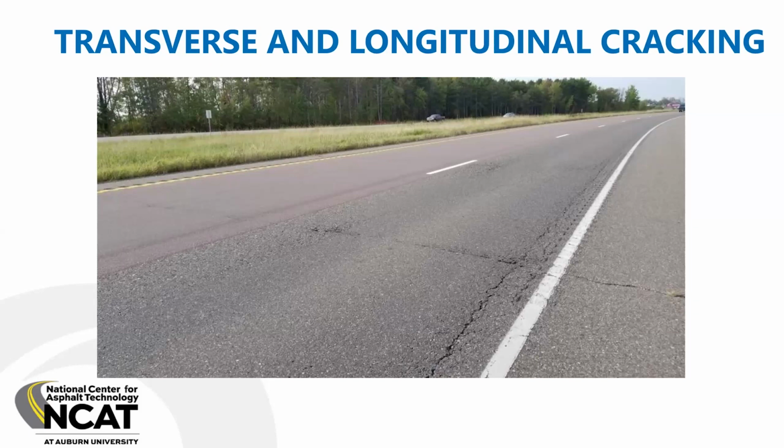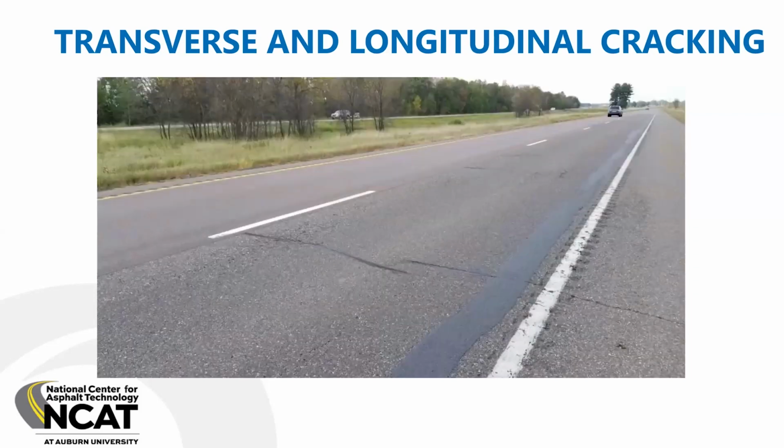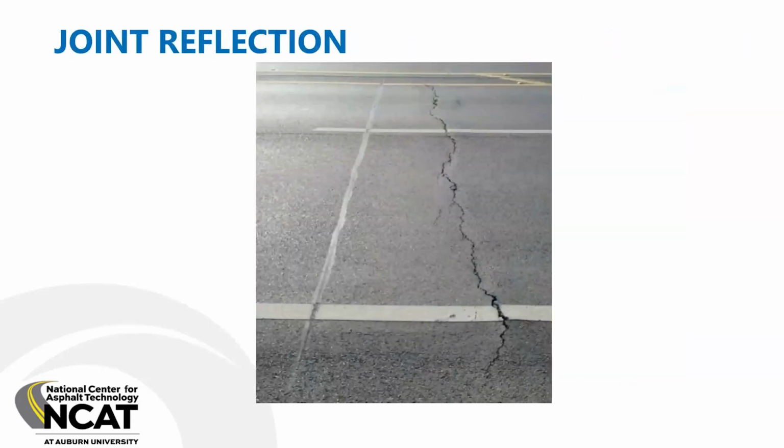So that longitudinal crack, because of the length of it, and it went all the way through this project, we did mastic patching, and this is a little better picture. You can see how wide the shoulder is, but we did mastic patching of that longitudinal crack, which is a highly polymerized kettle mixed type of a sand size mix, and we did rubberized crack routing and filling there, as you can see in that transverse crack. So these are types of cracks that don't fit the model of what I had previously described, and that's because of the climate and the practices up in Minnesota where that section was built.